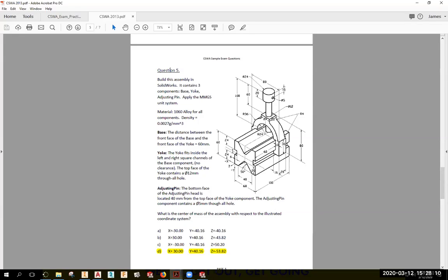It's up to you. Just when you assemble it, make sure that it's assembled with the right numbers so that this face is 60 back from there. So if you're modeling it in place, doing top down, model it 60 back. If you're doing it in separate pieces, just draw it, and then when you assemble it, make sure it's positioned correctly, okay? Any questions?